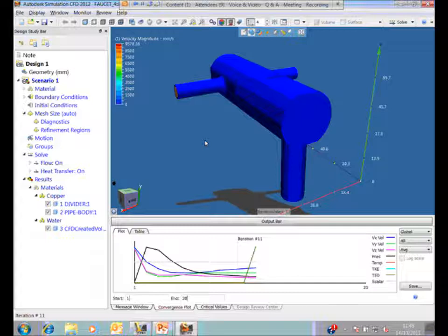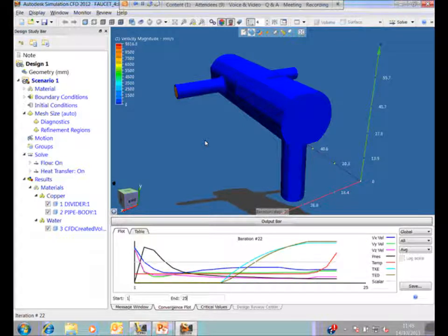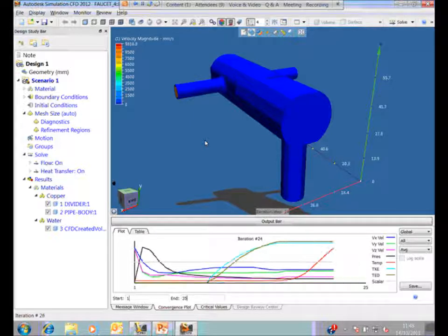We want to run this as quick as possible, but I would be concerned about accuracy unless I did increase this. After 20 iterations, it will then run a further 50% again and converge, just analysing the temperature. So you'll notice a red curve appear after 20 iterations once it's done the fluid flow analysis. And then the red curve will kick in, which will then do a convergence of the temperature of this analysis. And eventually this will plateau off. Again, we would really want to have more iterations for this and give us a result.